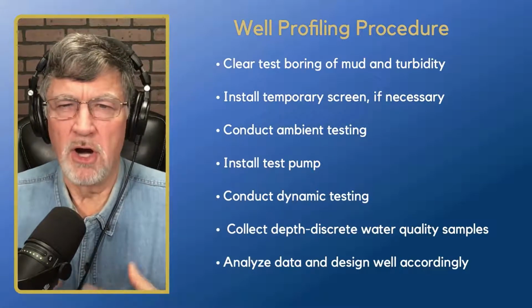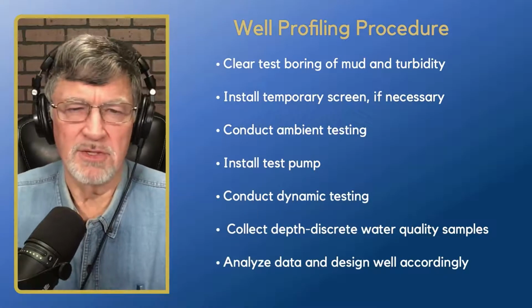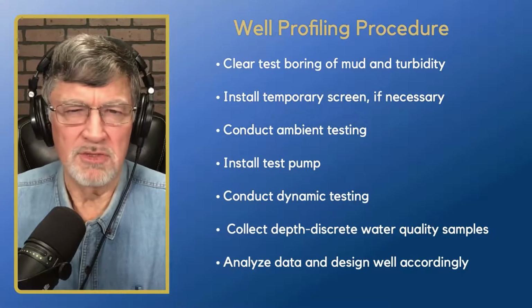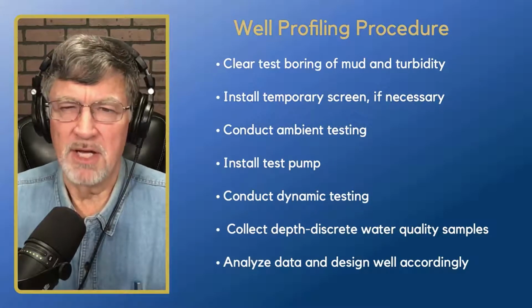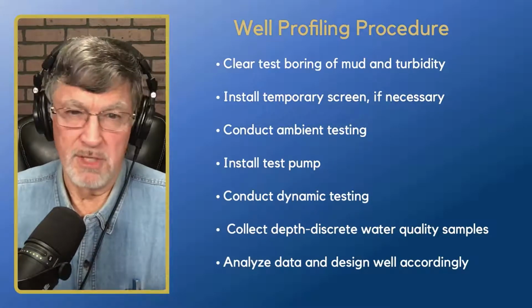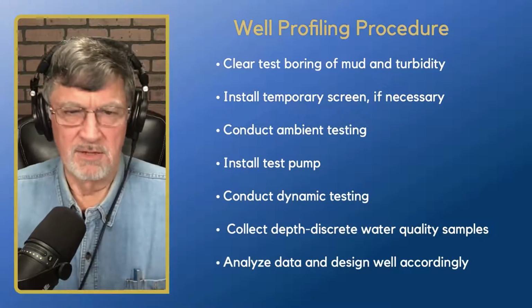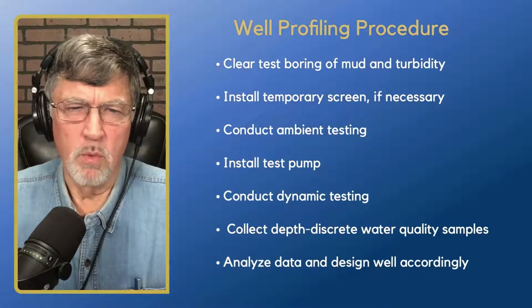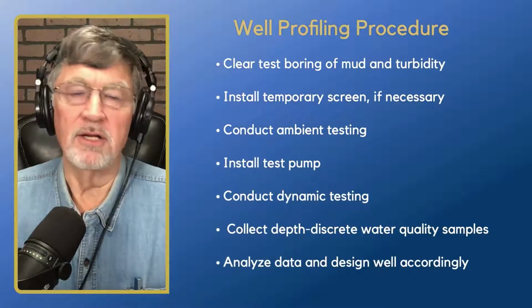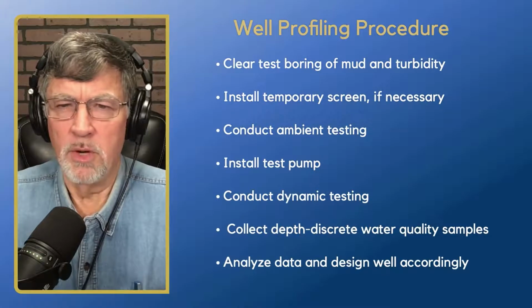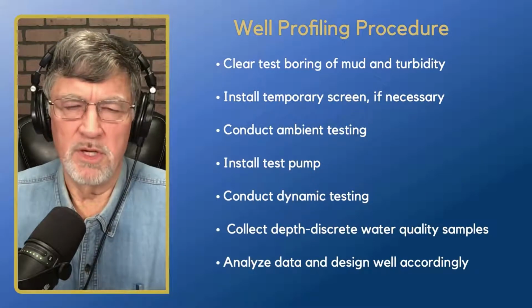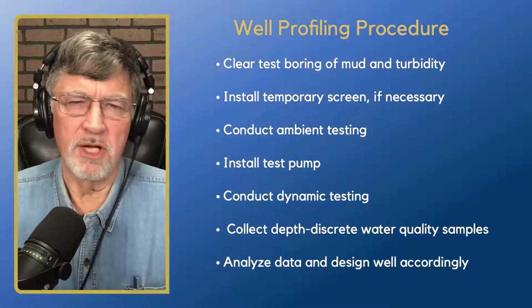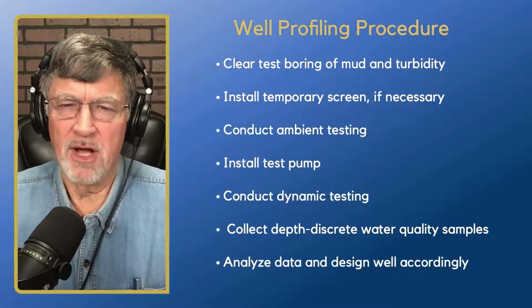You're going to install a temporary screen then if necessary. If you're in a fractured bedrock environment and you have a stable boring, this may not be necessary, although we've seen it sometimes where we get caving and stuff. We will actually install a temporary well screen. Pretty much required if you are in an alluvial aquifer. We don't usually build a well. We just use the temporary screen, so we won't necessarily put any sand pack around that.